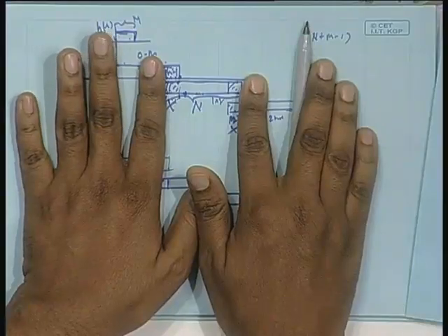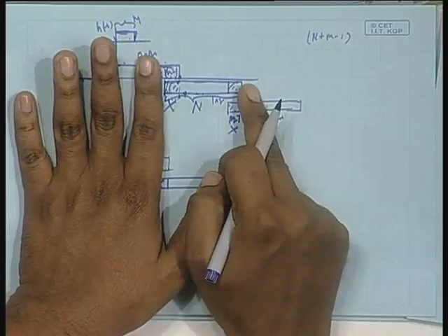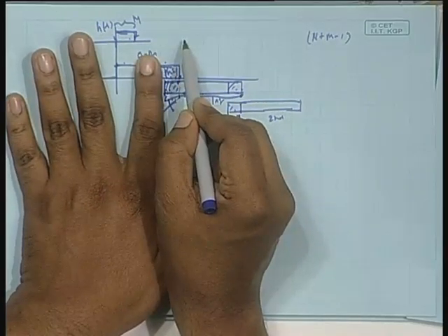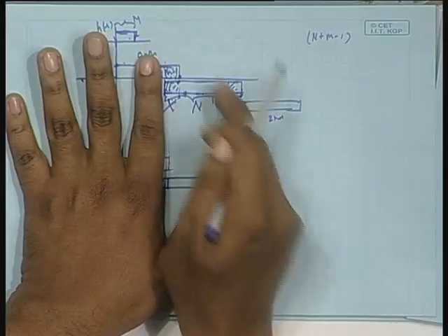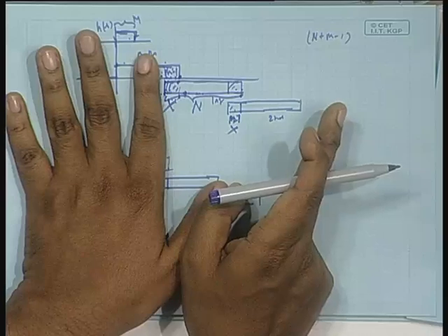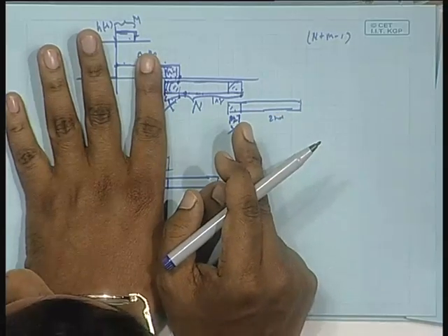I say that I can use simply an N-point DFT. This block you are convolving with this guy. This is a shorter sequence, this is a bigger, longer sequence. I will add only N minus 1 zeros to this fellow, and do circular convolution between the two blocks. I just showed you previously that even there you get an incorrect result only in the first M minus 1 points.